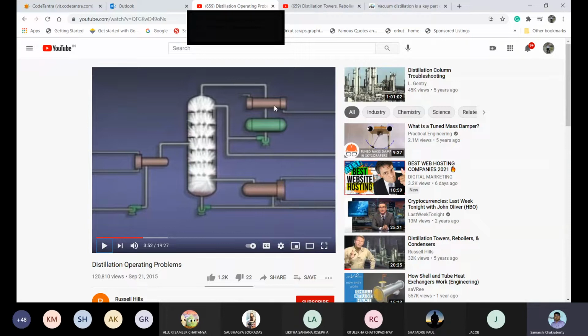So it will be directly sent to the reflux drum. So that is also one of the reasons. So you have understood how this type of flooding condition can happen under many circumstances: feed rate goes too high, temperature goes too low, reflux rate you are increasing uncontrollably without thinking about the internal design, and if you increase the reboiler temperature to a significantly high temperature, then a similar phenomenon can take place. So see how many factors can affect the performance of your distillation column.